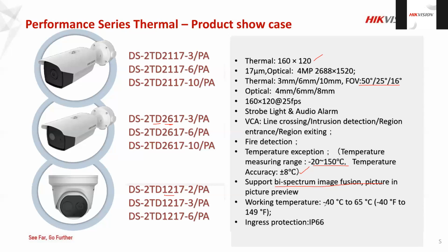And this is the normal working range, as there was a previous question from the audience. What is the working temperature of the device? So we can support from minus 40 degrees Celsius all the way up to 65 Celsius. So we have to keep in mind, if you are fixing this in an area hotter than 65 Celsius, you have to consult us, and there can be other special models which can tolerate high temperatures. So this is how normally things are.